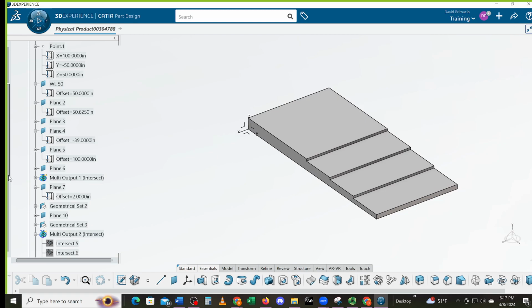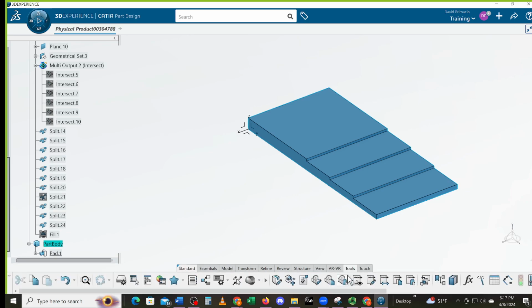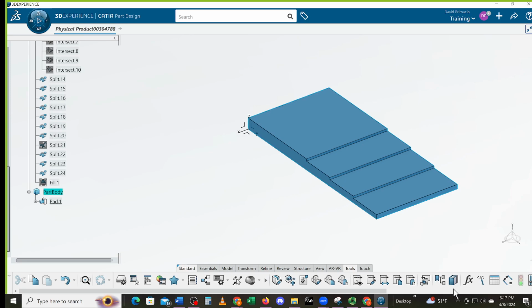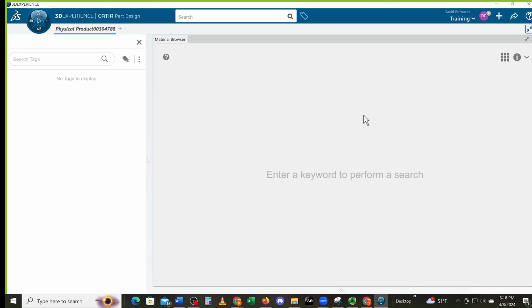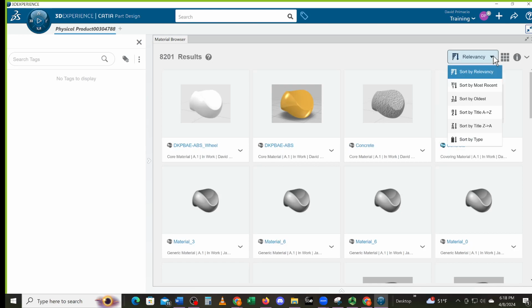And when you found your weight and inertia, you picked part body, not pad, part body. And then you hit tools. Oh God, I don't have aluminum applied. Who had the wrong weight? I think Stuart was saying he didn't have the same weight. Is it possible that there was an incorrect material? Like if you double clicked on the material and then checked what the listed density would be?